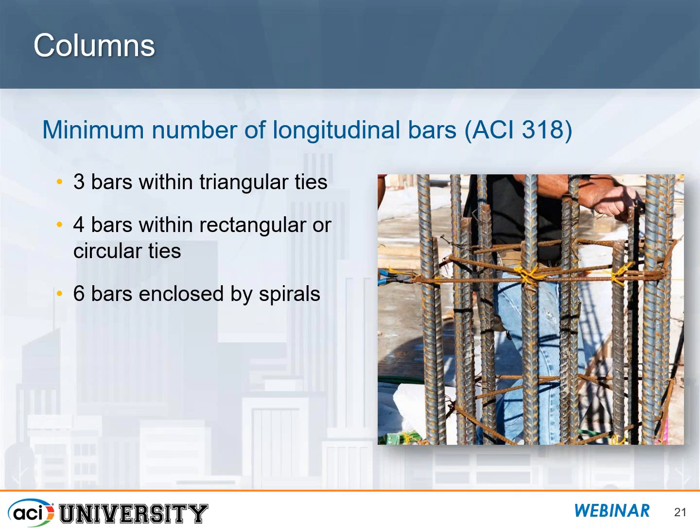If you have a rectangular column with rectangular ties, having less than 4 bars obviously doesn't make sense for a lot of different reasons, especially constructability. So what happens sometimes is a confusion between ties and spirals when it comes to circular columns, and this helps us to make sure we don't have to provide any more bars than what we actually need.